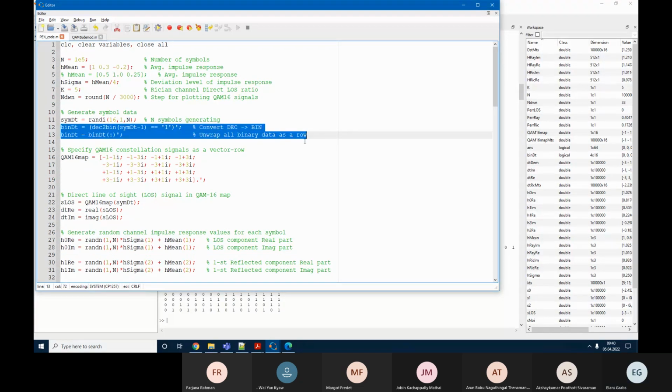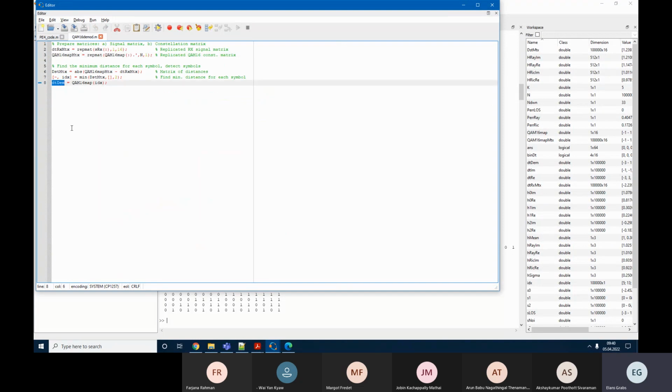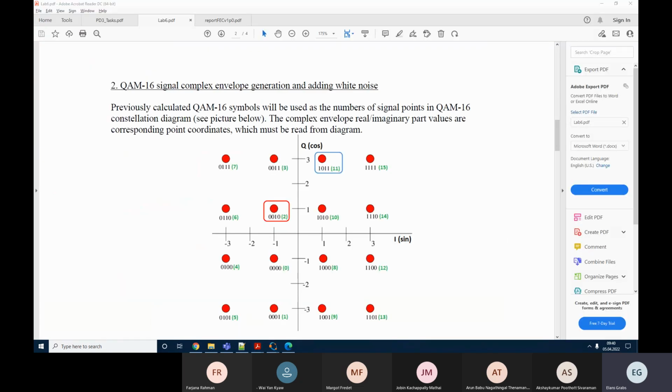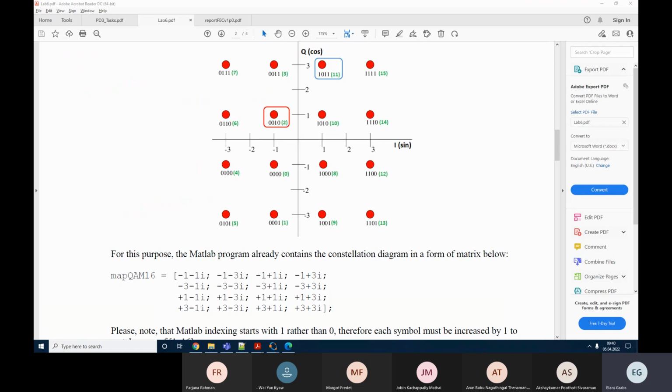So here, once we have this demodulated data, oh, wait a minute. Actually, this index is already the answer we seek, because this index shows the number of the constellation point, which happens to be the code itself. I did so intentionally in this constellation by assigning to specific points specific code words. Basically, you can say that I was reading this constellation on purpose, starting with not this point, but with the point having the smallest number and ending with the point having the highest number. So here and here, and they all go in consecutive order. That's how I was organizing this map so that this code word in decimal form can be used as an address. So that was the whole idea of this process.